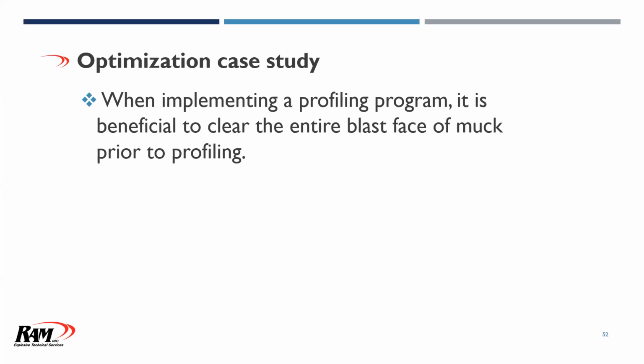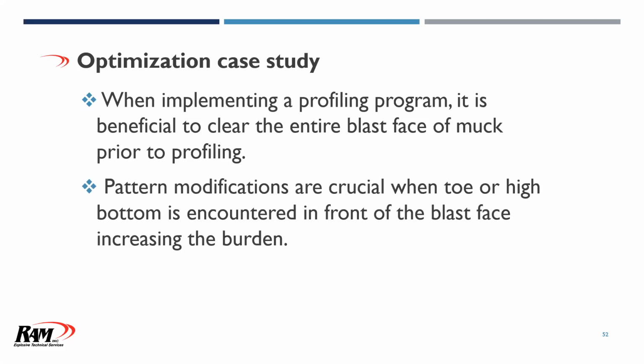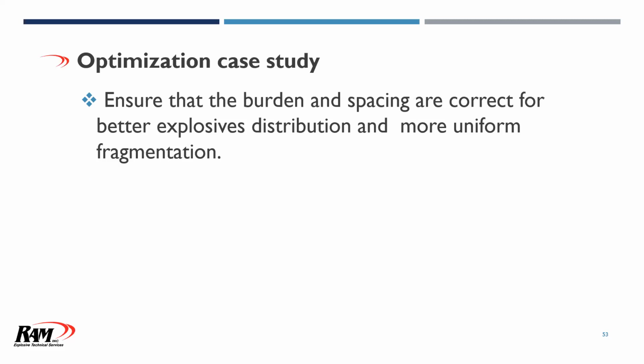And you'll see that one of the first things they realized is they had to clear that entire face of the muck, which I know is a big, big challenge for a lot of operations due to limited area, due to scheduling and just getting it coordinated. But again, when they cleared those faces out and they designed the shot according to the actual face, the improvements came very, very quickly. And when they saw toe problems or issues down there, they were able to make those adjustments, whether it's angle of hole, how they approached it, how they shot it.